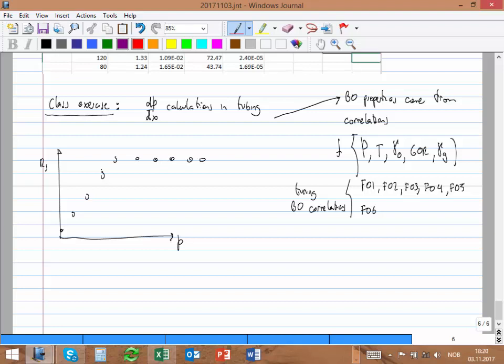And when you apply the correlation, you, for example, obtain these points, okay? And then you can use these factors to try to tune and get closer to this line, with these FO factors. We're not going to look into it, but that's actually what you do, because correlations were developed only for a particular group of fluids, either North Sea, California crudes, Middle East, etc. And you always have to tune these correlations so they better represent the measured data.